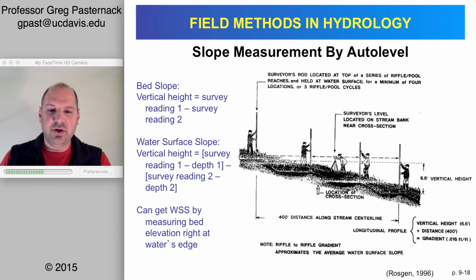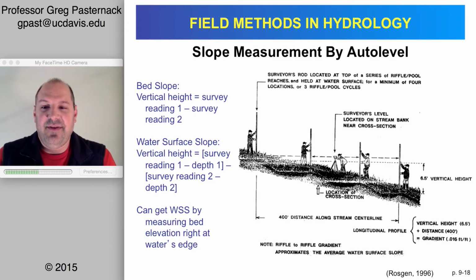You go to the first location, upstream or downstream, to wherever you're going to walk, and you make your first measurement. Remember that when you measure from the upstream end, you're going to be measuring your smallest number on the graduated pole. So let's say that has a value, it could be anything, a value of 1.25 or whatever, in whatever units you're working in. And everything is going to be relative to that.